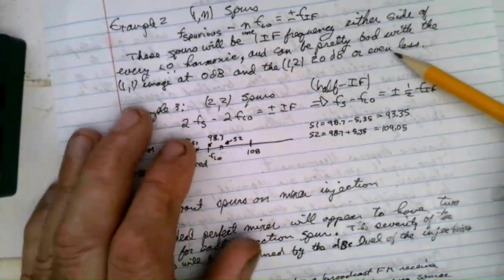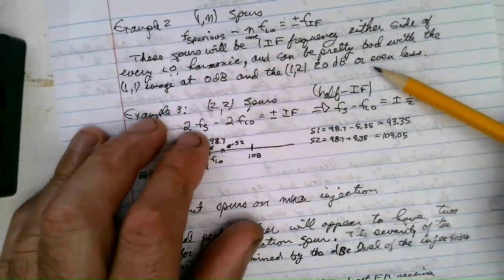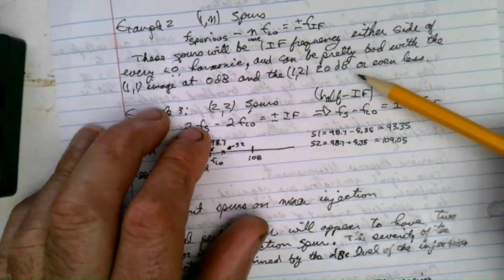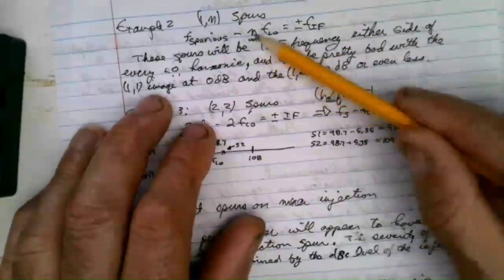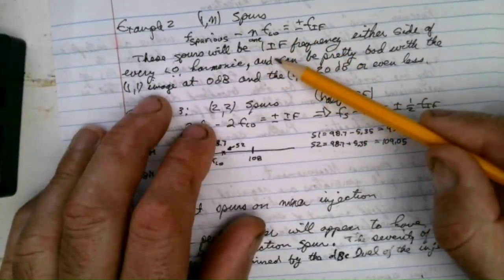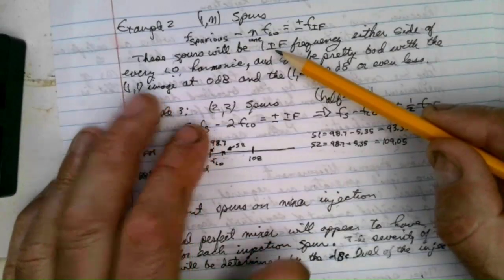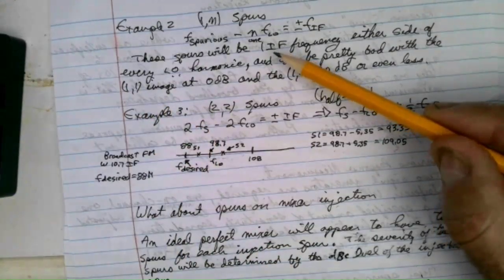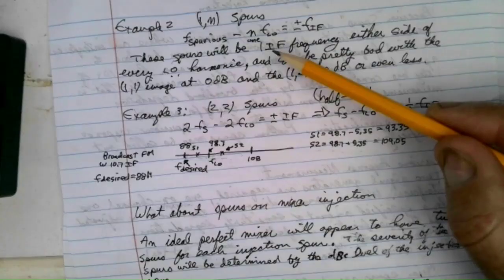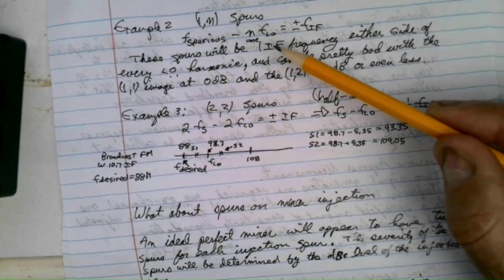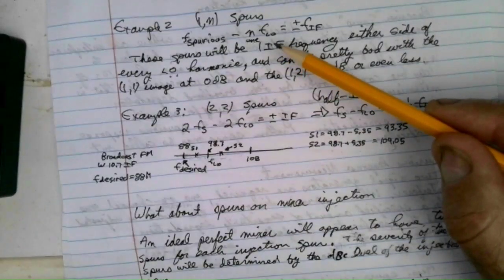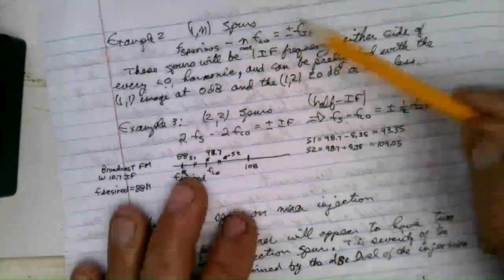And by the way, for those of you that are sampled data people, this particular process right here you would call aliasing. Basically, you've got something that's up around the third harmonic of your clock that ends up aliasing down into between minus Fs over 2 and plus Fs over 2. The same thing as mixing.